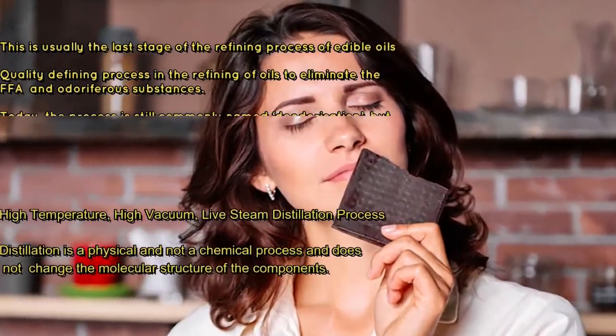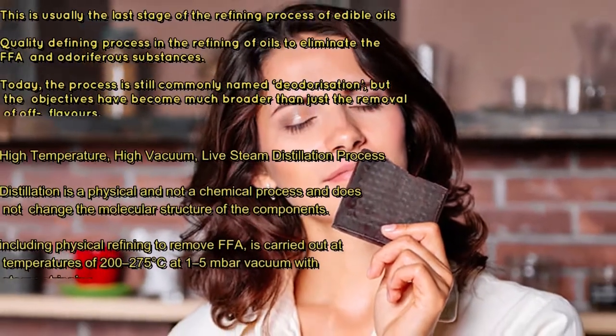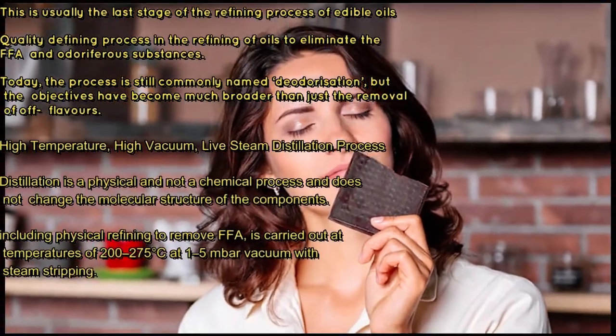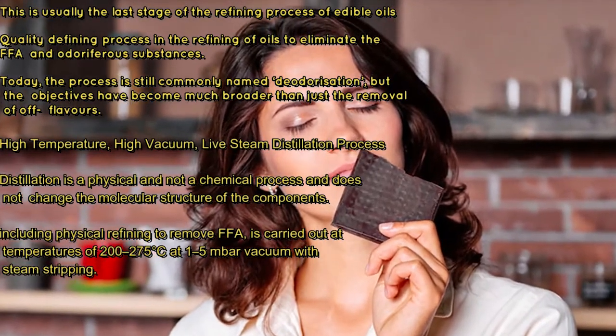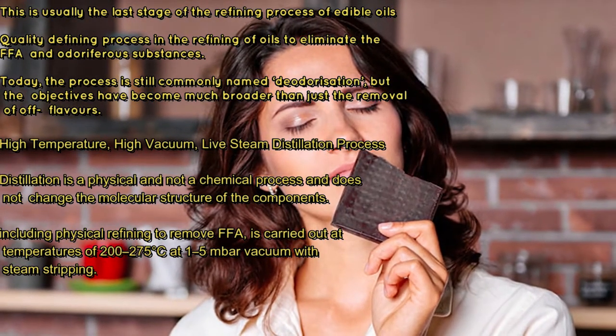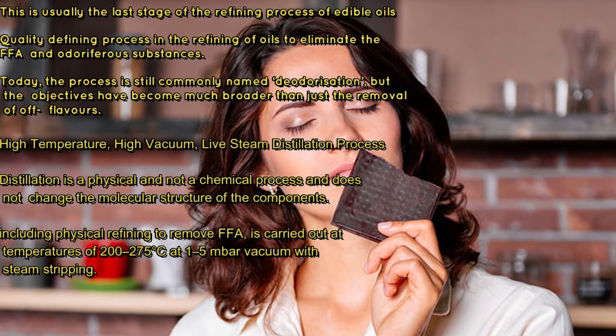Deodorization is the last stage of the refining process. It is a quality control process of oils by eliminating the free fatty acid or FFA and any substance that can give off flavor or smell. The process usually involves high temperature, high vacuum, and live steam distillation.